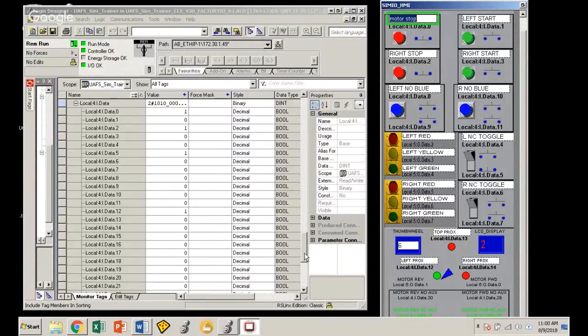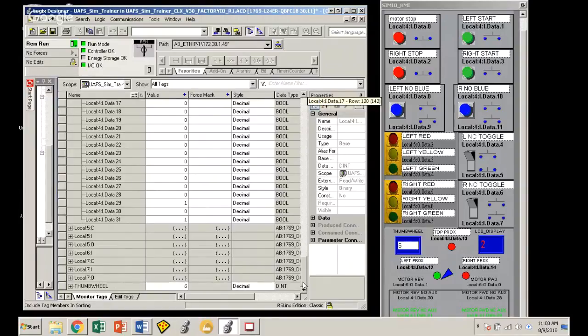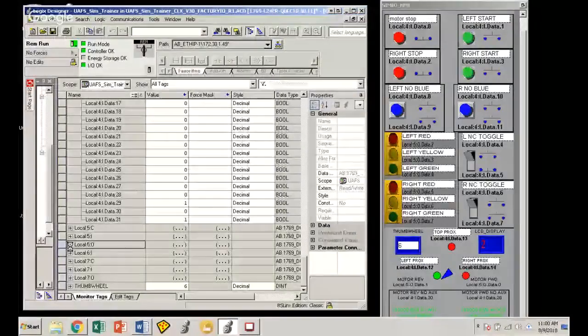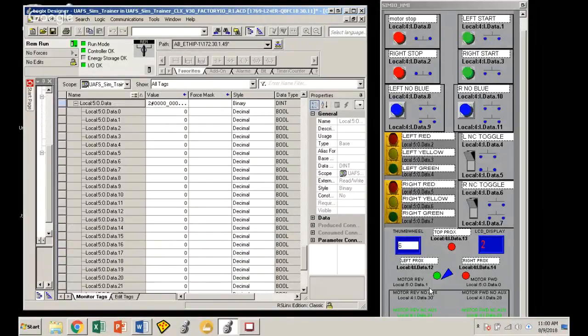We're going to come over here to output card 5, and we're going to open up the data. I'll see that that is actually .1 and .0. If I just simply put a binary 1 in here, I can see that our motor begins to spin. As it makes our prox indicators, they begin to highlight, and so I can write code programming those for any kind of usage. So, quick example program.